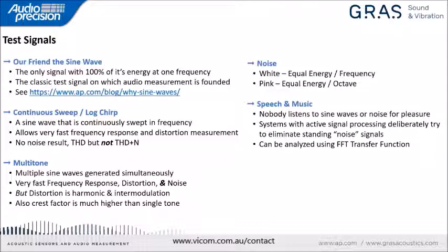There's another approach. We're still going to test with a sine wave, but what if we tested with all the sine waves at the same time? So there is the multi-tone technique, and this is literally we generate a bunch of sine waves simultaneously and we play them simultaneously. And we can capture the frequency response, the distortion, and the noise response of a device.